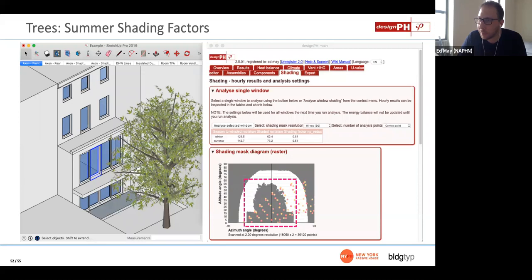Dan said, I know it's not a common issue, but how do you incorporate elevated train tracks into the SketchUp model? That's a good question. We would try and model them in. It's not uncommon. We work mostly in New York, Brooklyn, Jersey City, Hoboken. We have all sorts of weird shading contexts. You can get a lot off the internet, but at a certain point, you're just going to have to actually model it. So you're going to have to take some site measurements and take some photos, get on the site and actually build those out.